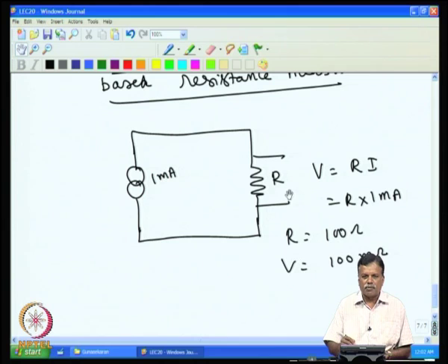That computation can be done just by scaling, or if you have a processor based unit, actual computation also can be done. And this is also linear, unlike the Wheatstone bridge technique, where the unbalanced voltage is not a linear thing. Unbalanced voltage is non-linear. So, this looks better from the measurement point of view, but then there are drawbacks in this.